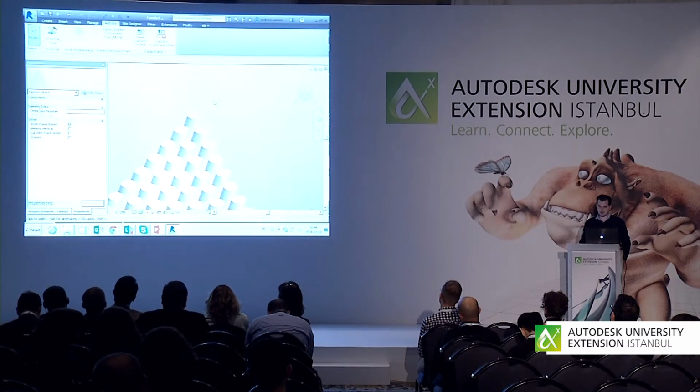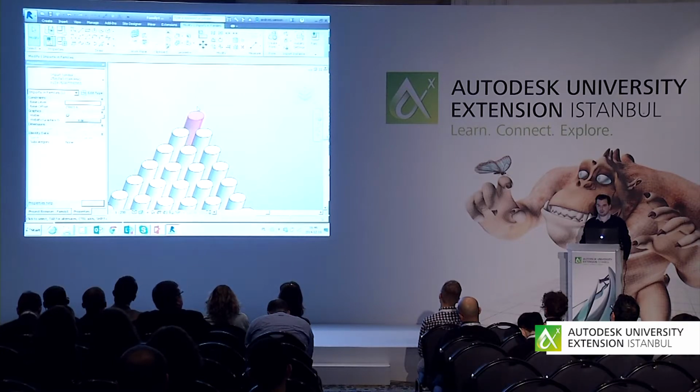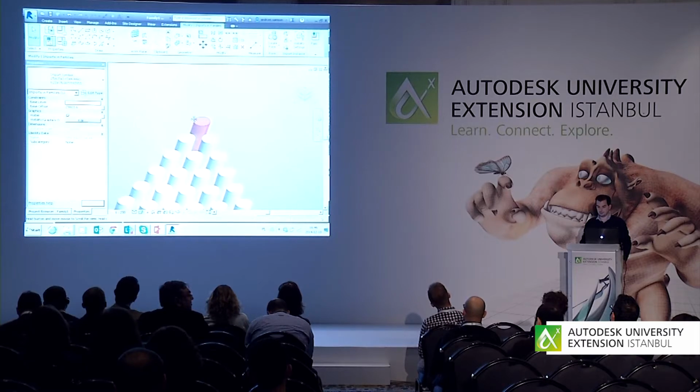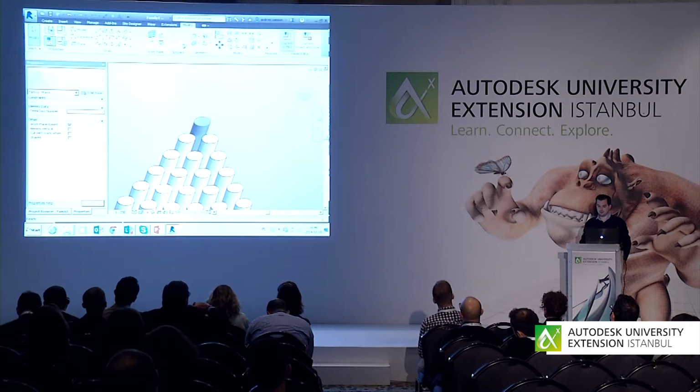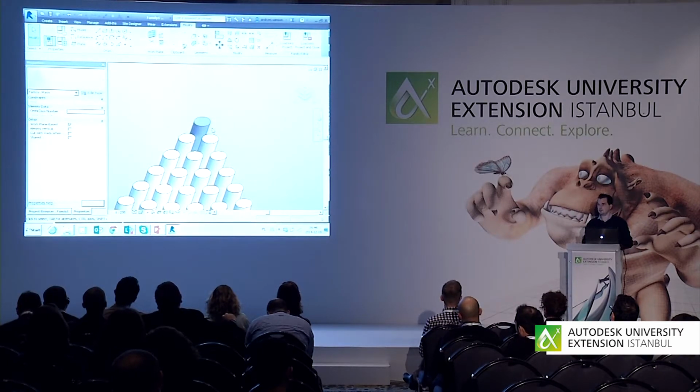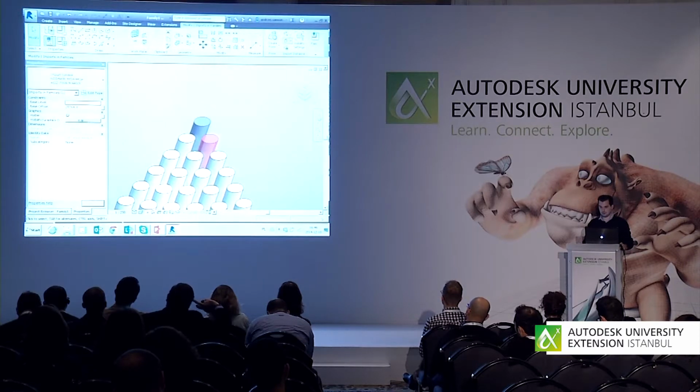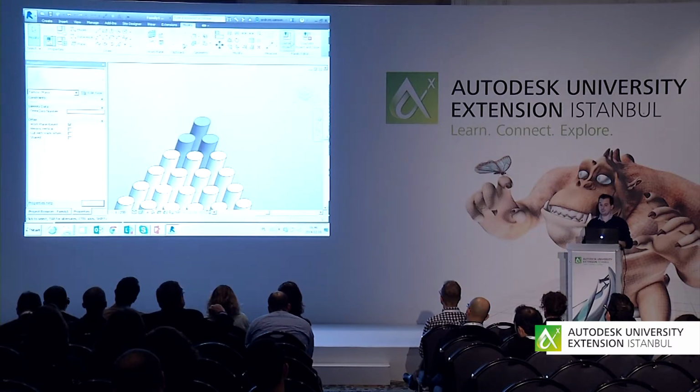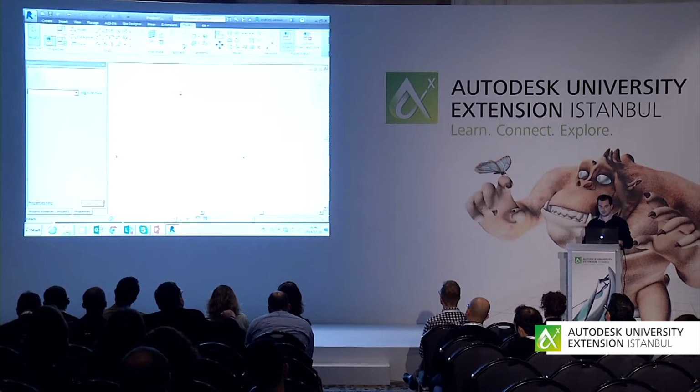And what happens is that, because obviously this cylinder is not really complicated even for Revit, what you can do here is explode this element, and then if the geometry permits, it will convert it automatically into the Revit native geometry. So you can explode some of them. I'm not going to explode all of them. And then you load it into the project.